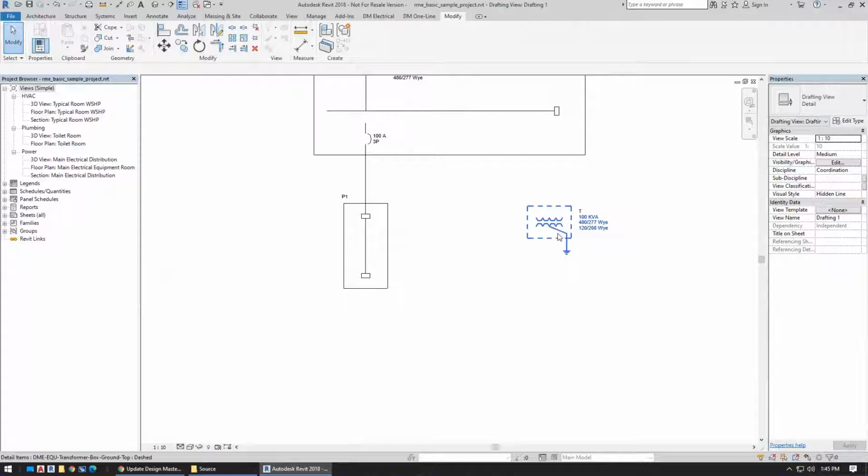That's what we made all of our families in. And in the future, as we drop support for versions of Revit, when new versions come out, we'll convert our families to the newer version. For speed's sake, we do actually make copies of the families and convert them when you put them into newer versions. So if you're working in 2021, we take the 2018 families, convert them to 2021 files, and make a copy on your computer so that we're not converting them all the time. So we'll convert it once, and you'll see that happening. But then in the future, we'll use that cached version. And then if you go make changes to the family, we'll see that it's changed, and we'll update the cache. So always work in the lowest version of Revit that you're going to be working in.